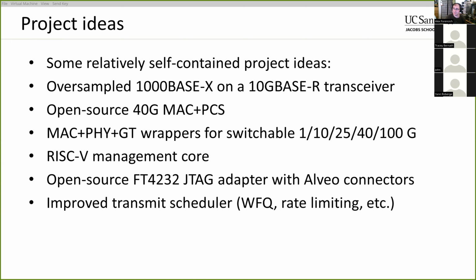And it's also nice if you can just load over JTAG and have everything work, because you could always run into situations where you've loaded a new design over JTAG, but for some reason the RISC-V loaded its firmware out of flash, and that's some other random version, or it got confused about something that was in flash and tried to load that. It opens up a potential for a bunch of weird issues. Which is what happened with the base platform for the Alveo boards, right?